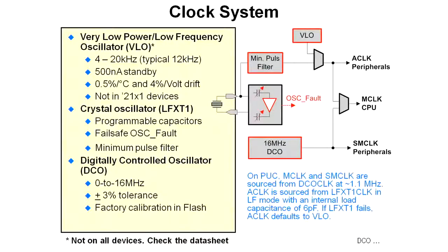There's a minimum pulse filter on there as well, and restrictions as far as what crystal you can actually put on the outside of the device. The DCO, the digitally controlled oscillator, doesn't require anything connected to it. It does its thing completely internally.